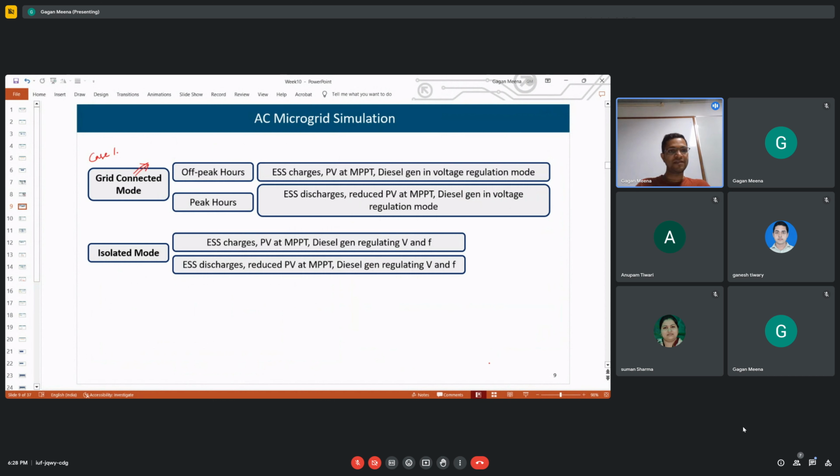They are connected using this dual active bridge, which connects the first microgrid and the second microgrid. Both are autonomous microgrids, and one advantage of this interconnection is that these two microgrids need not operate at the same voltage level. They can have different voltage levels, as in that case study. This first one was operating at 380 volts, and this one at 48 volts.